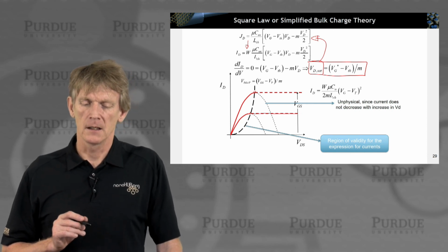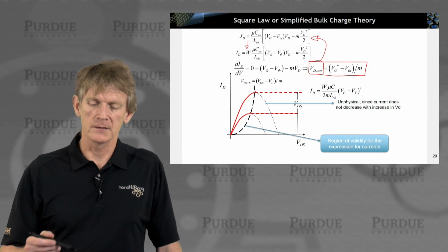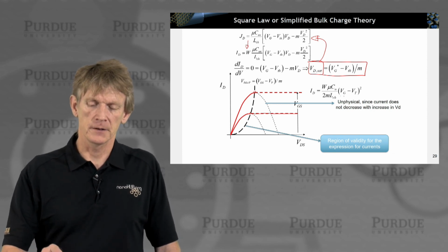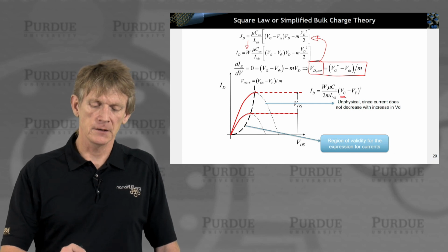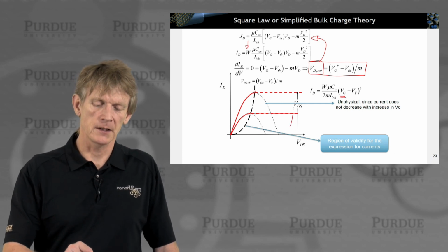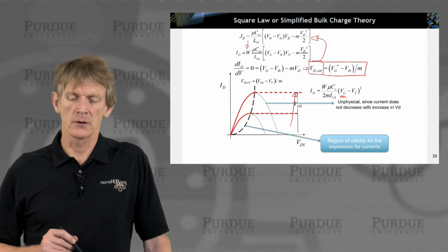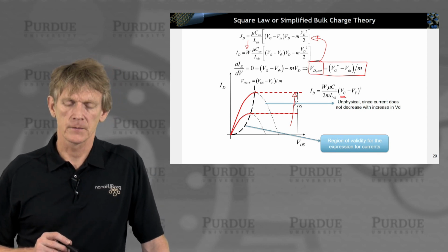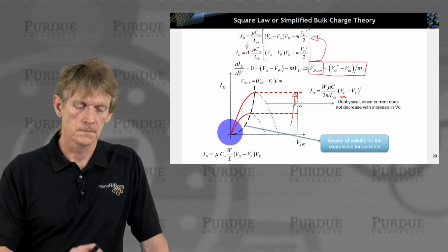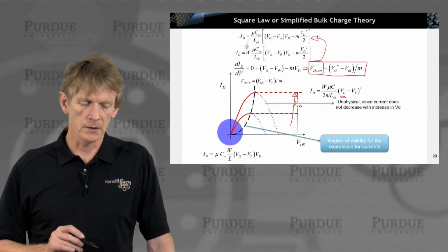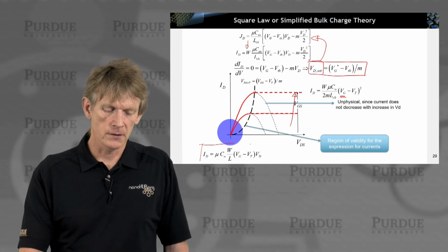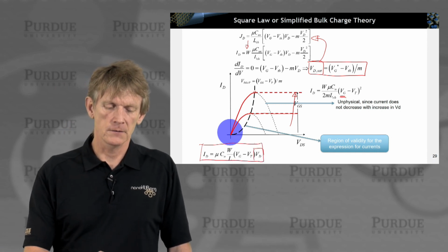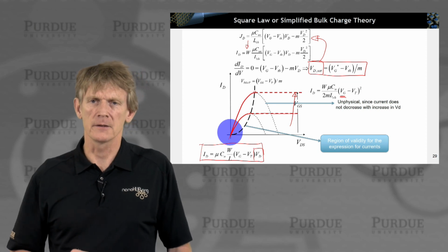And that saturation current rises up as a function of gate voltage, okay? So here, given a certain source drain voltage, you basically ramp up the current as a square of the gate voltage. Okay. Down here in the turn-on region, the drain current goes linearly as the drain voltage. Okay, so this is a linear behavior down here.